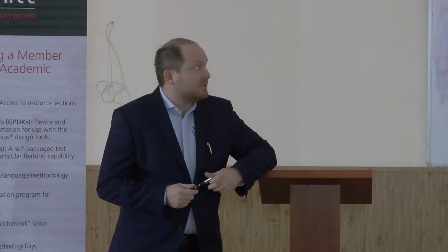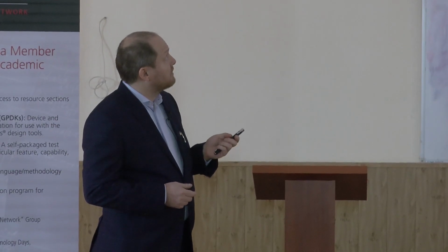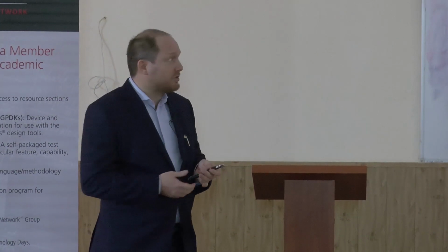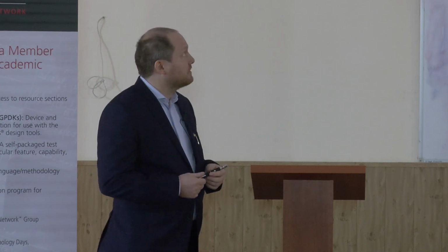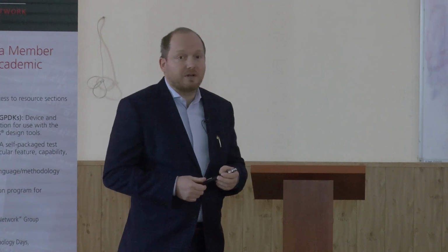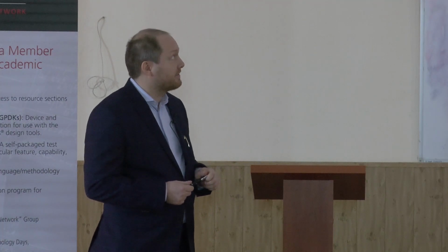So this is no longer valid. That means that in 20 nanometers, if you want to add a second or a third core, then the cost of the processor will increase again. But still, big companies like Apple are still going further down the geometries. And why? Because if you compare to 16 nanometer, the same performance comes at 18% less power consumption for 10 nanometer, and for 7 nanometers it's even 35% less.